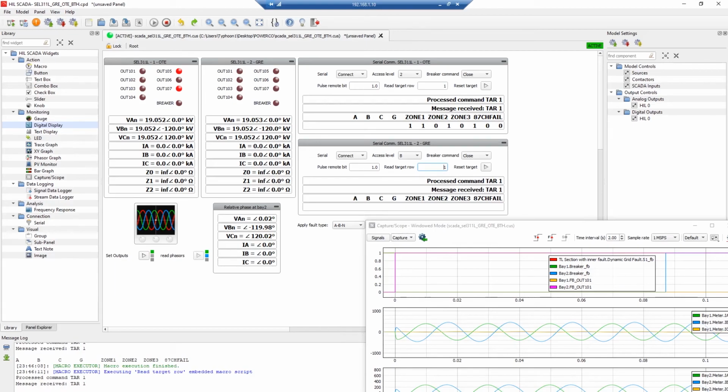Okay, so the relay on bay 1 understood that it was a fault AB to ground. That's correct, and it understood that it was a fault of level 2 or within zone 2. It could explain why it actually operated faster than relay on bay 2 at this time, but relay number 2 recognized the precise fault, AB and ground, but it didn't recognize the zones. So I think in this case it might have tripped once more on that.